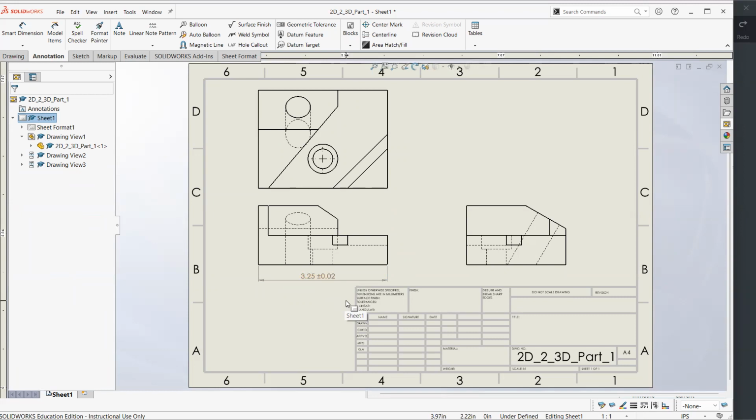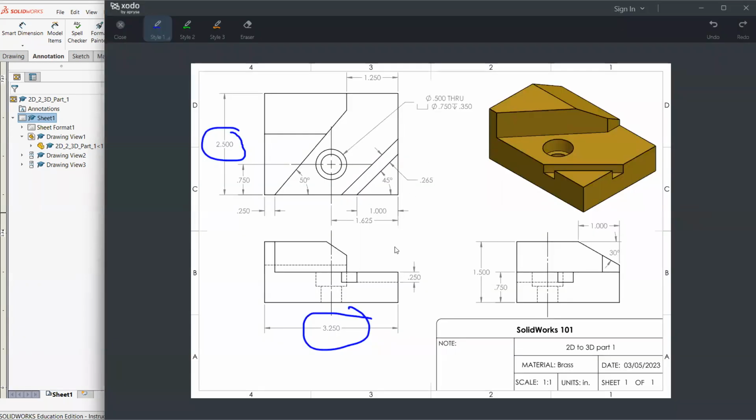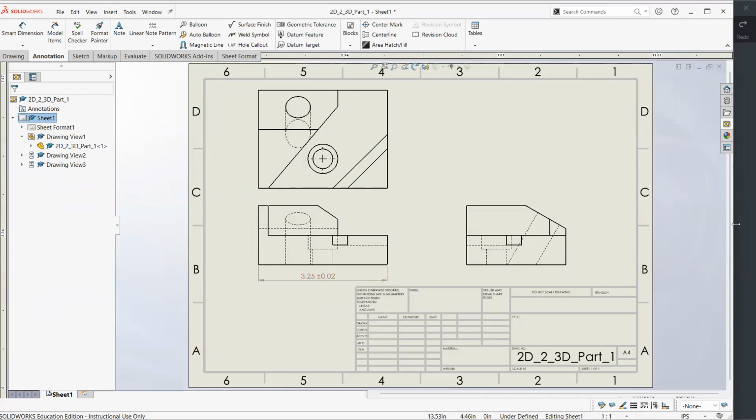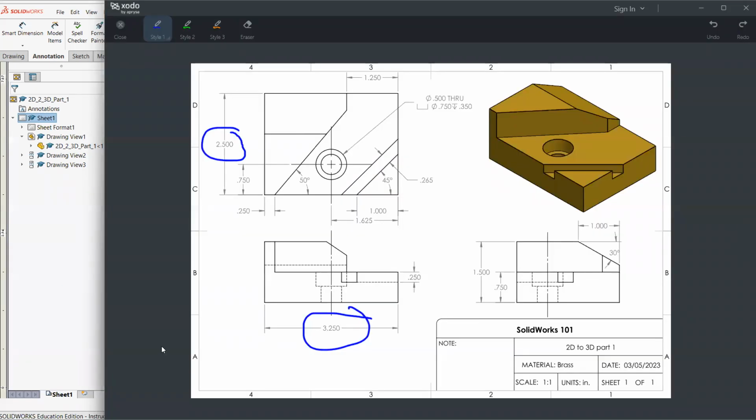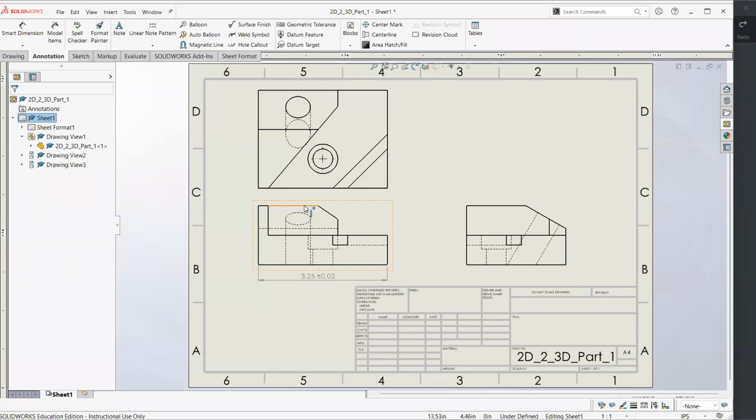And so this is one of the things as engineers that we need to focus on when creating our 2D drawings to be manufactured in various factories, is that we need to have all the dimensions and features given, as well as tolerances that are acceptable, and the tolerance should be as high as possible so that the part will be as cheap as possible while at the same time being functional. And with this, we are done with our class for today regarding the different options and tools that are available when we are creating our 2D drawings.